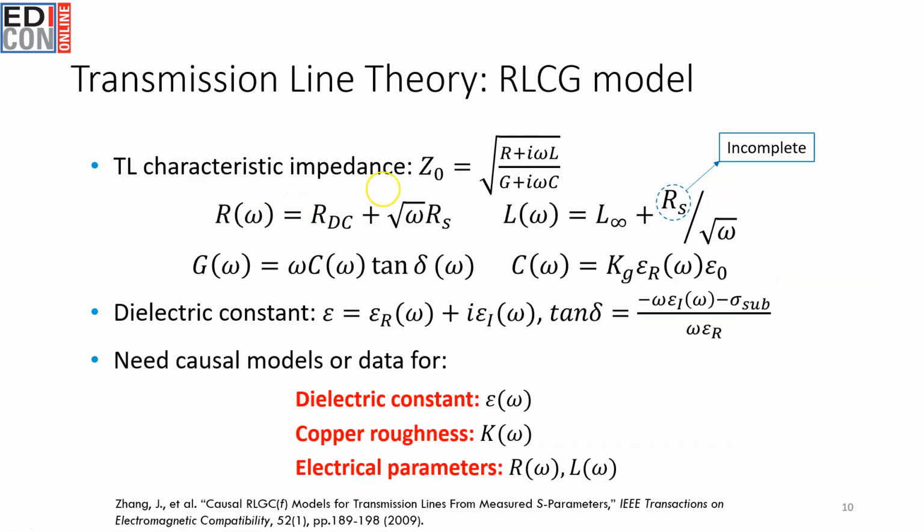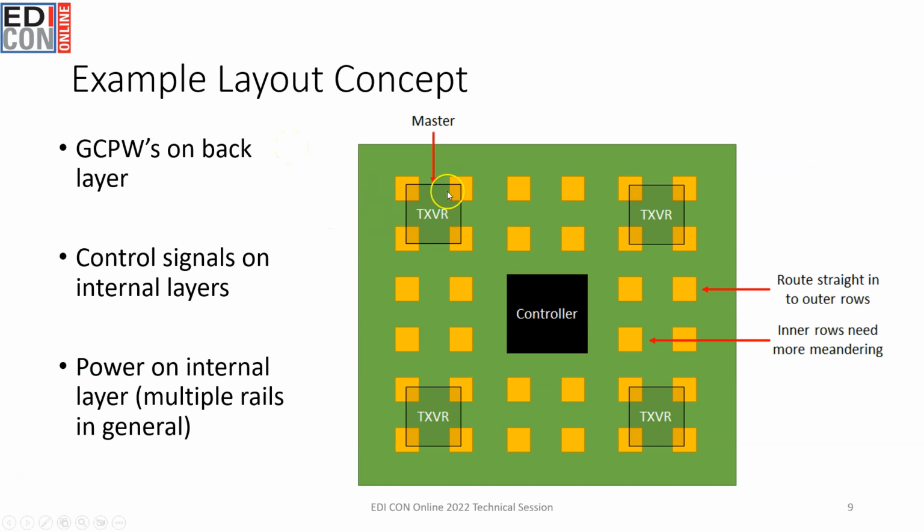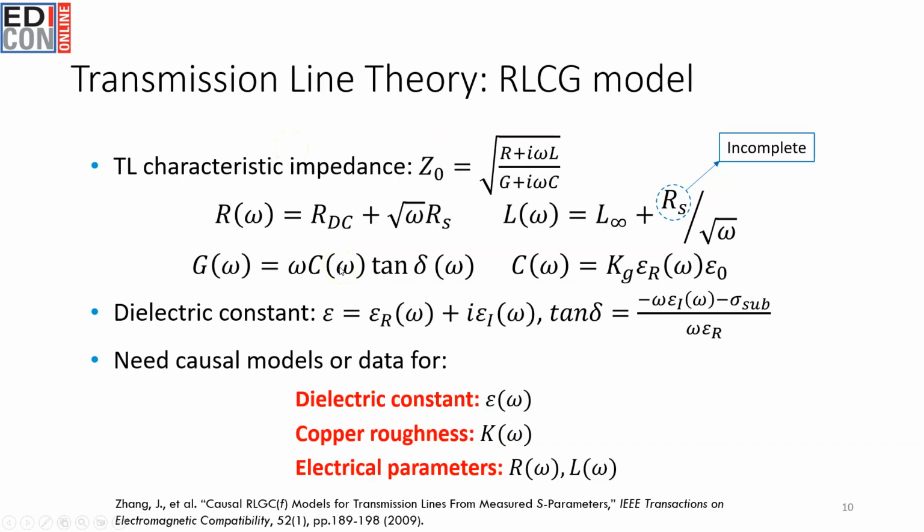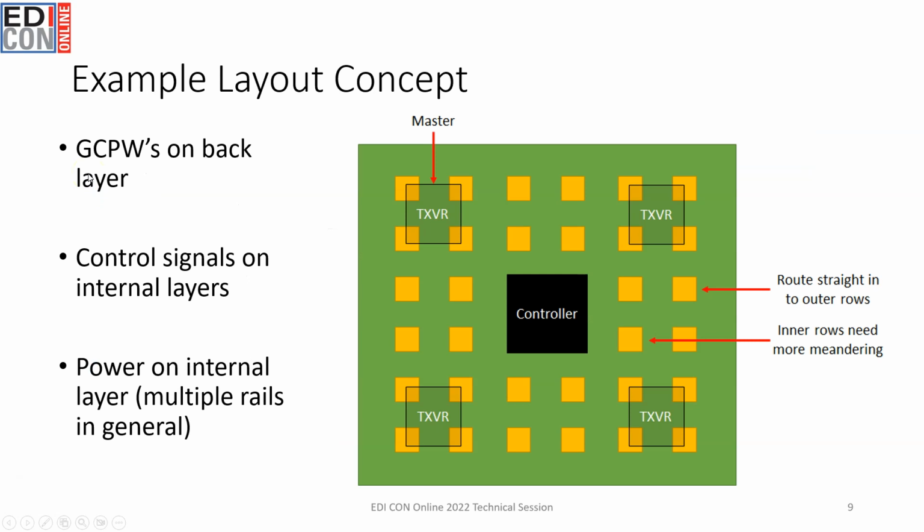So all of those transmission lines that you have to route between all of these transceivers and all of these elements, they have to be very precisely designed according to the stack up that you've used in the board. In this type of design where you have the antenna elements on one layer and then the transceivers on the back layer, you tend to have a hybrid stack up, so that you've got a low loss PTFE material on the outer layers. Then the inner layers can usually just be an isola low loss laminate or even just standard FR4 if you're talking about separation between the power and ground rails.